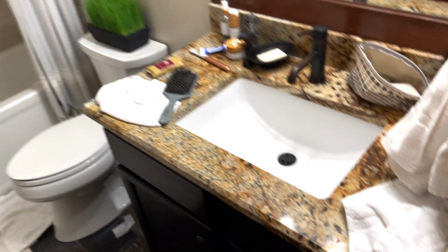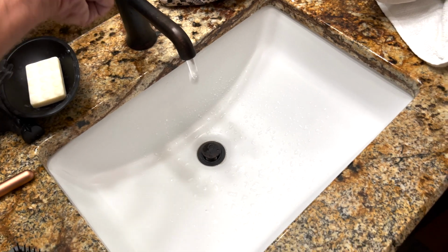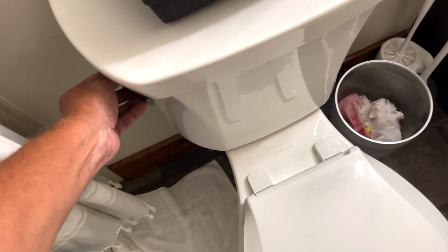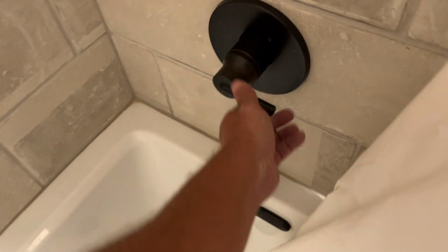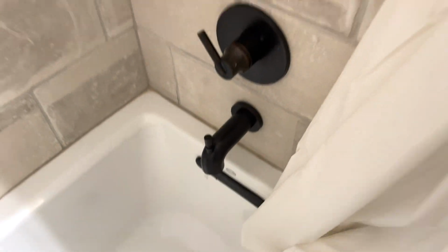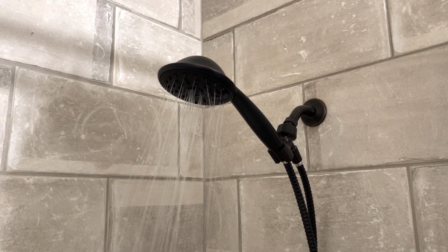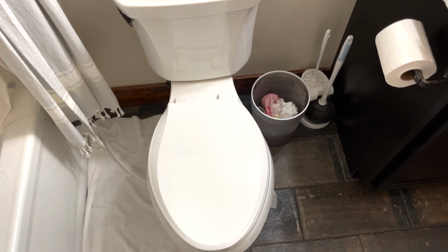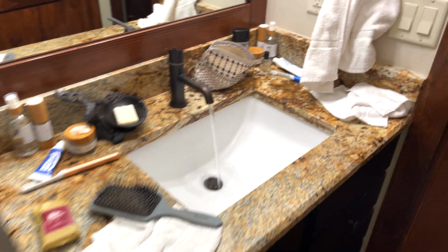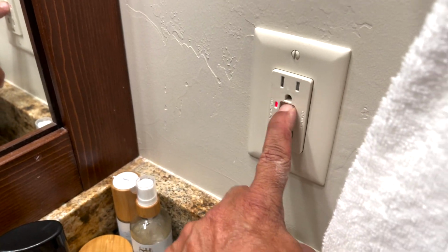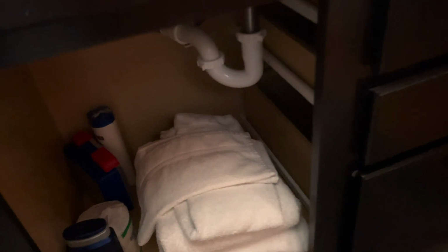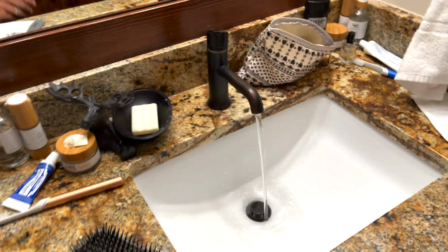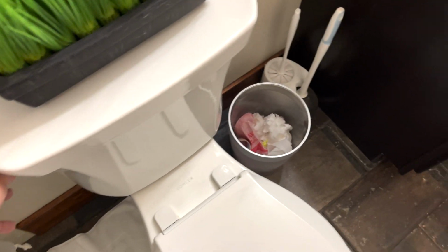Bathrooms. I do all the bathrooms just about the same. This is a 3-bedroom, 2-bath house. Run hot and cold water at the fixtures. Flush the toilet a couple times. Tub and shower, and make sure there's functional flow at the shower head. GFCIs in the bathroom. And look for plumbing leaks at the pipe and the valves. And make sure that the toilet doesn't move on the floor.